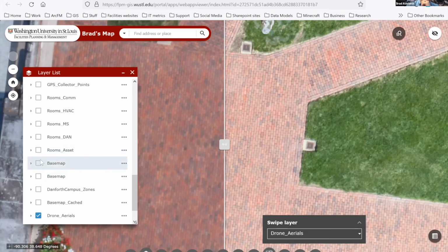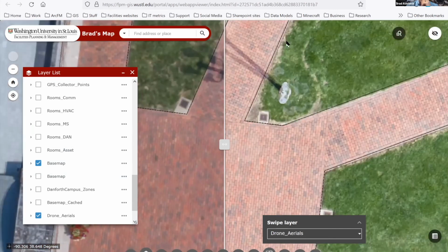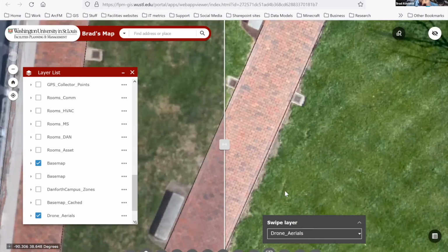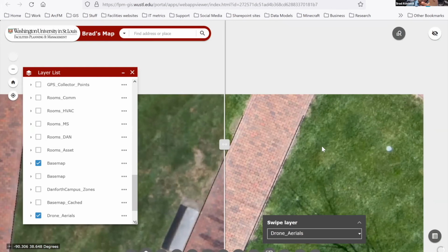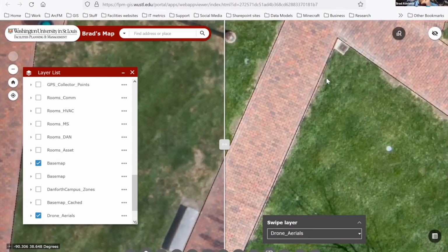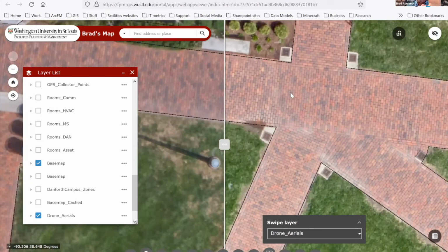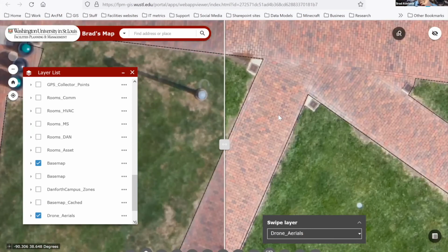But if I go here and I look at the base map data, you can see this is actually all of our line work. This is what I was talking about. You can see it lines up exactly with the sidewalks. And that's how we do our data validation to make sure that everything is scaled correctly and located accurately. Because you can have it positioned somewhat correctly, but you still need the scale correct. And that's what's nice about seeing that the sidewalk fits inside of both lines, right? Because you know that it's scaled correctly. It's not just shifted to one side, so it's positioned correctly, but it's also the right scale for things. So if you wanted to take measurements, the measurements would be fairly accurate.